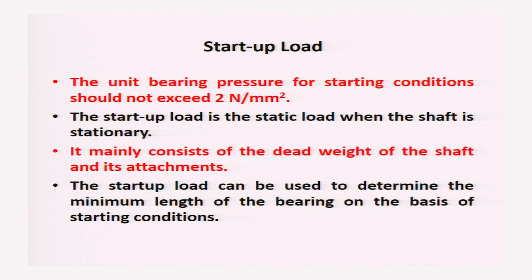Now, the startup load: during startup, what should be the load? The unit bearing pressure for starting conditions should not exceed 2 Newton per mm square or 2 megapascal. That means the static load W static divided by LD should be less than 2 megapascal, and this was given by Trumpler also.